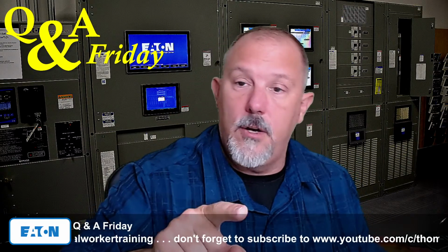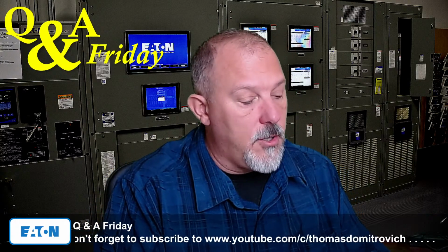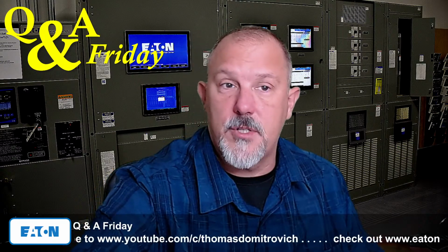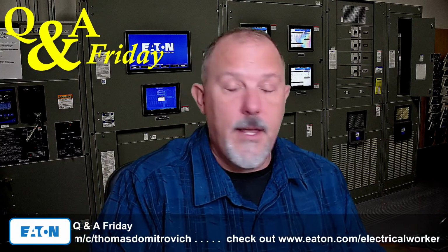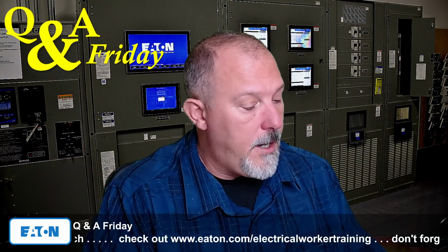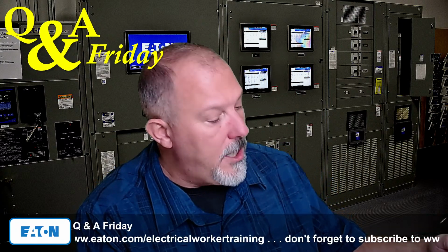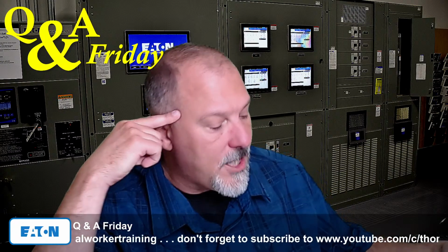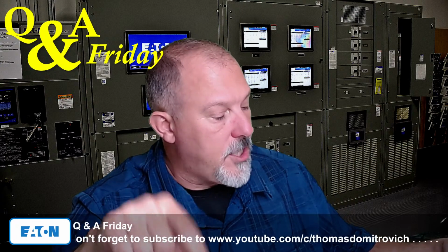And in this video there was confusion. I had some individuals who were saying, look, because I locked the cover and it is no longer a 1200 amp breaker, it's a 1000 amp circuit breaker, I no longer have to do 240.87. And what we showed was that's not the case because it can be adjusted to a higher rating. So what we say in 240.87 is where the highest continuous current trip setting for which the actual overcurrent device installed in a circuit breaker is rated or can be adjusted is 1200 amps or higher.